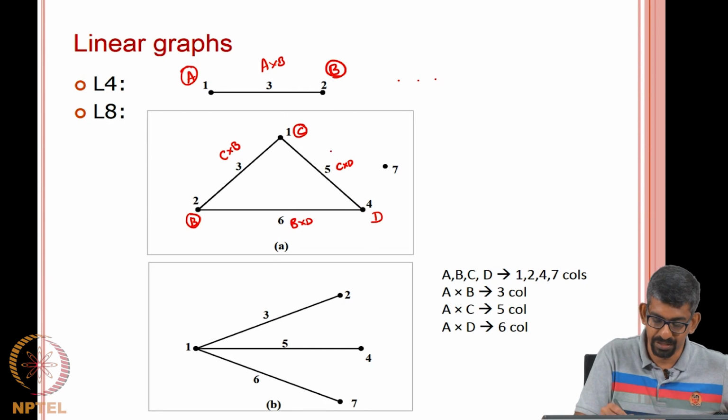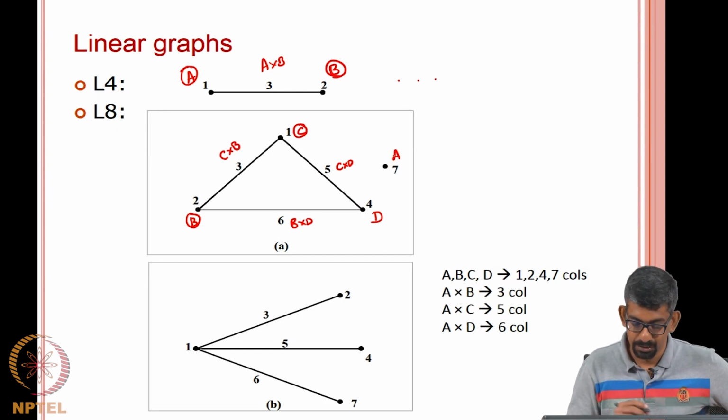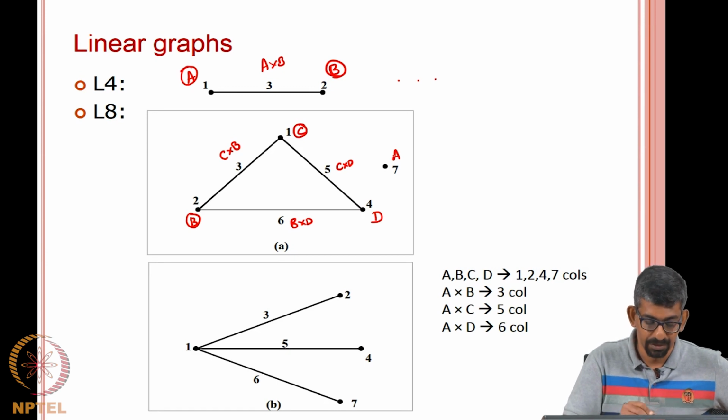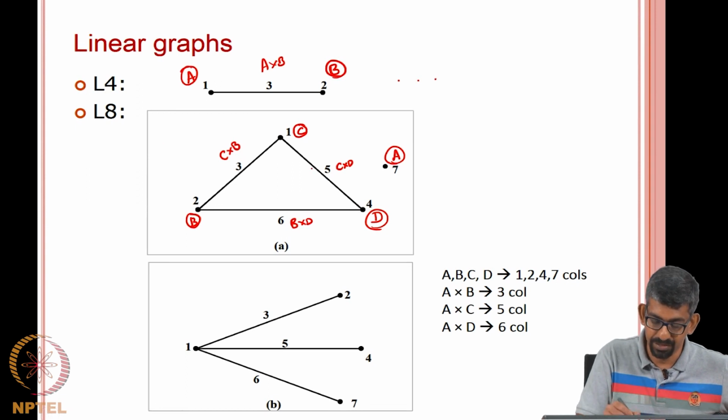So, 2 factor interactions with 3 factors gives you 6. Then this one could be my A. So, this is one possibility for an L8, meaning 1, 2, 3, 4, 5, 6, 7. So, L8 means 7 columns. So, 7 factors is something that I can account for.